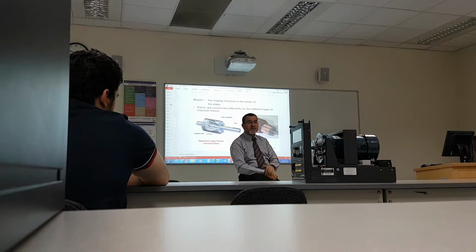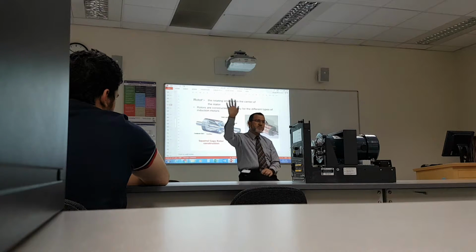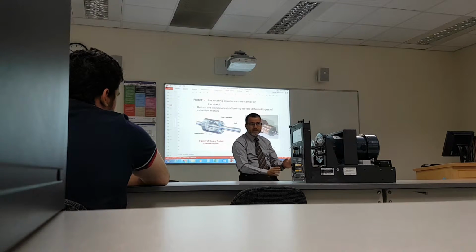If it is overexcited, it means more excitation than it needs. So it gives up some reactive power. That's why it becomes higher than 1 power factor. Underexcited, less than 1. Overexcited, more than 1 power factor. Normally excited, 1.